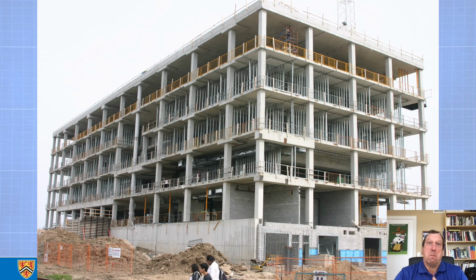if you have the money to pay for it. Now, I don't want to make it sound like moment frames are really expensive. They are expensive to pull off in some kinds of wood and some kinds of steel. But it's quite simple and inexpensive to get a moment frame in reinforced concrete design, because the rebar and the pouring of the concrete makes the joint connected, and it's pretty straightforward to put the steel in such a way to transfer moments. So buildings made of reinforced site cast concrete routinely use rigid frames as a way of stopping the building from falling over. And so here we have E5.